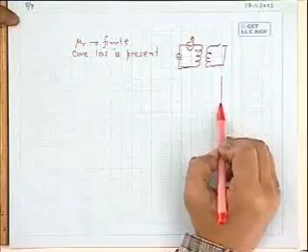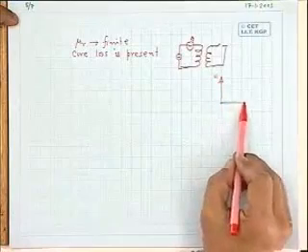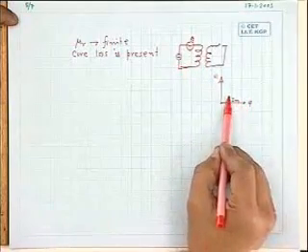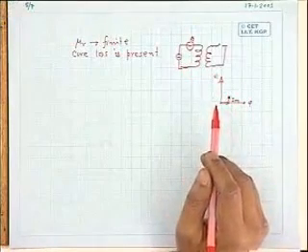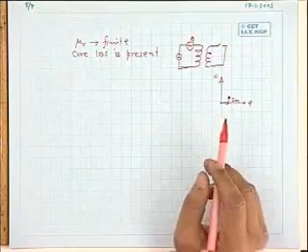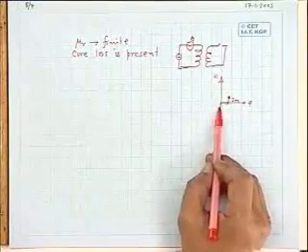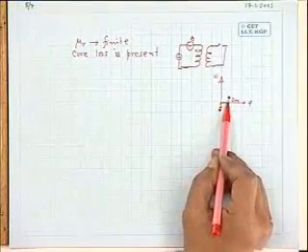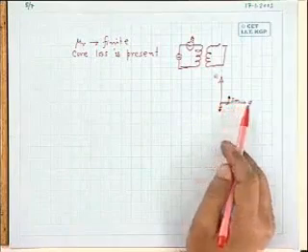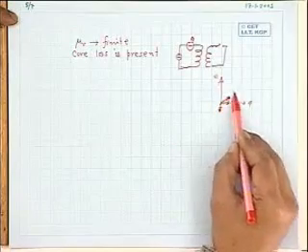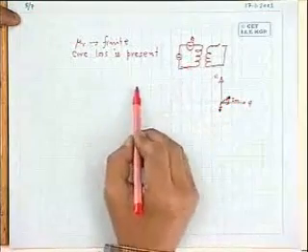Because in eddy current, this way we can think. Suppose this is your applied voltage, and this is the flux produced, 90 degree. Some Im is there. But apart from that, because of the core losses, there will be some reflected current. The eddy current loss, for example, is just like loading the transformer with another coil, which of course we don't want, but it happens inside the core of the transformer. There will be as if some secondary current, and this will dictate the primary to draw some extra current. So the induced voltage in the eddy current could be represented by some eddy voltage, some eddy current in this actual core, and it will have its reflected part like that. So the transformer is as if loaded whether you like it or not, secondary being open. And also some wattage should be drawn from the supply.